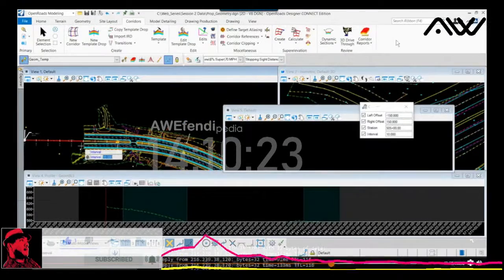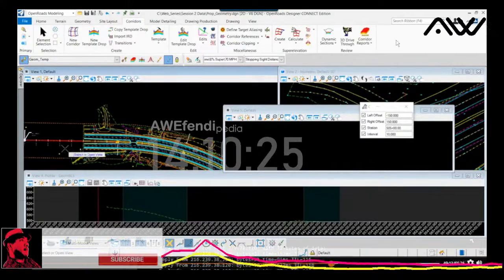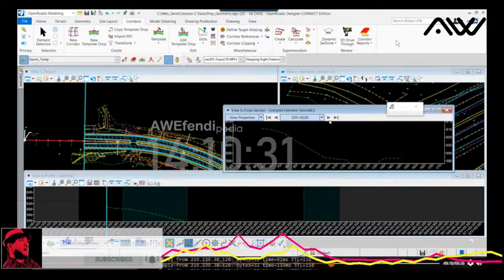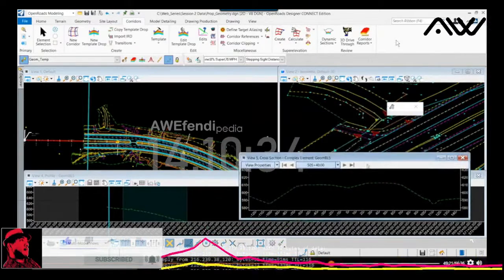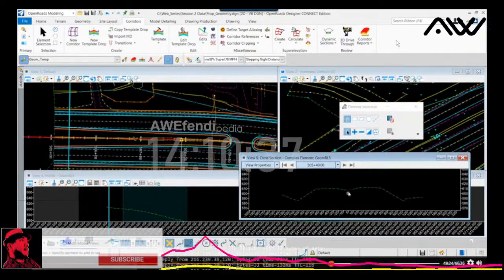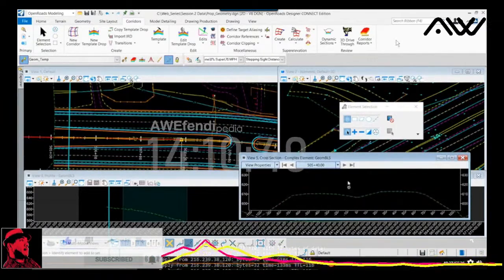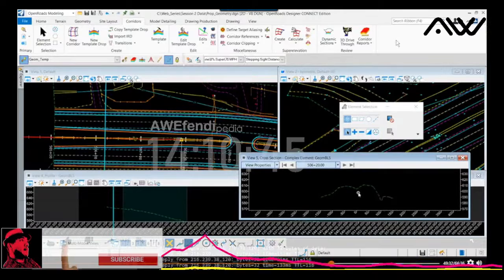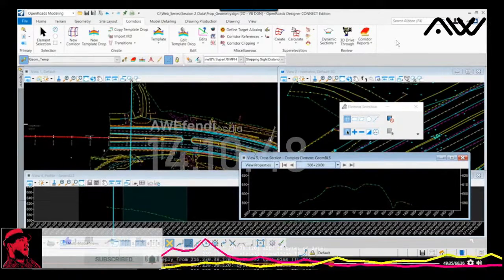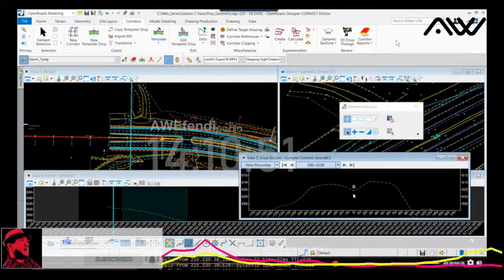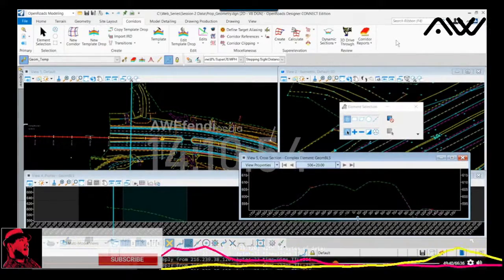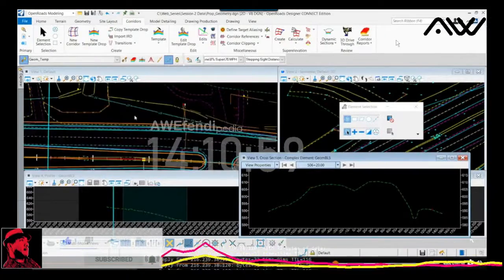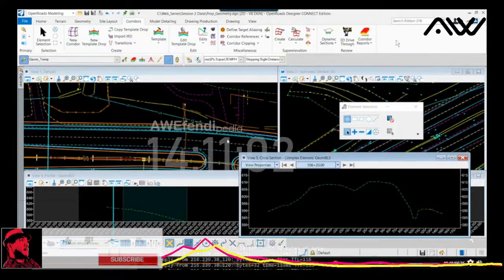And data point in the view. And so now we can see those sections, and we can scroll through and see visually now the sections as we begin to work as well. Now, the sections have bearing on what I want to show you. As we cycle through here, if I exaggerate this a little bit, you'll notice, again, the elevation difference between here. We want to minimize the elevation difference between the two sides of the roadway in our new corridor. So again, we want to hold a widened inside edge of pavement. Now, how am I going to locate that inside edge of pavement horizontally and vertically?